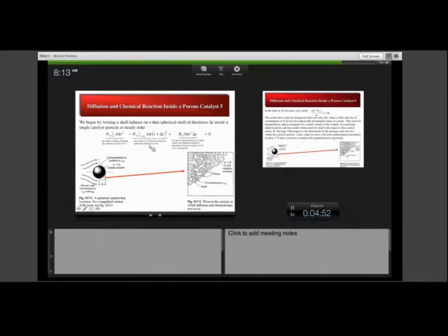But the key issue is that the pores and structure inside this catalyst particle, those structural features, have to be small relative to the size of the catalyst particle itself for this analysis to be rationally applied. And so, with that in mind, we can write a shell balance on a thin spherical shell going from R to R plus dr inside this catalyst particle.